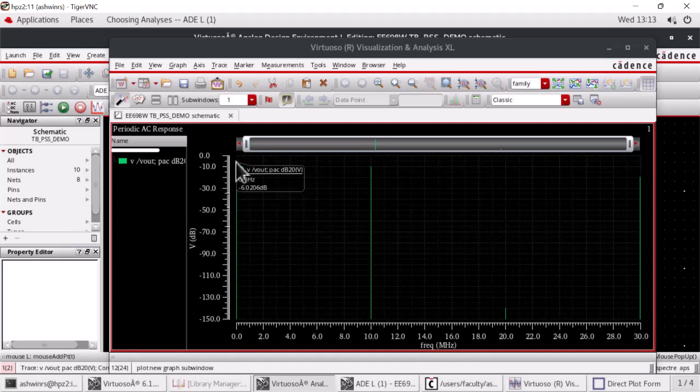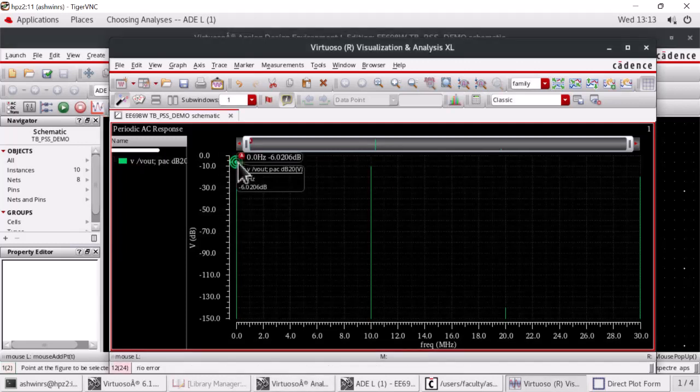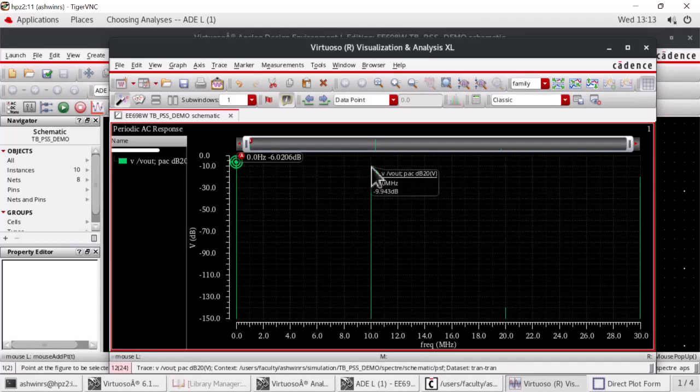The strength is, I don't know if you can see, minus 6 dB. Let me see if I can mark it. Yeah, it's minus 6 dB, and that's what you expected, right? Half. And this is the tone at Fs, from DC to Fs, and that's minus 9.94 dB.